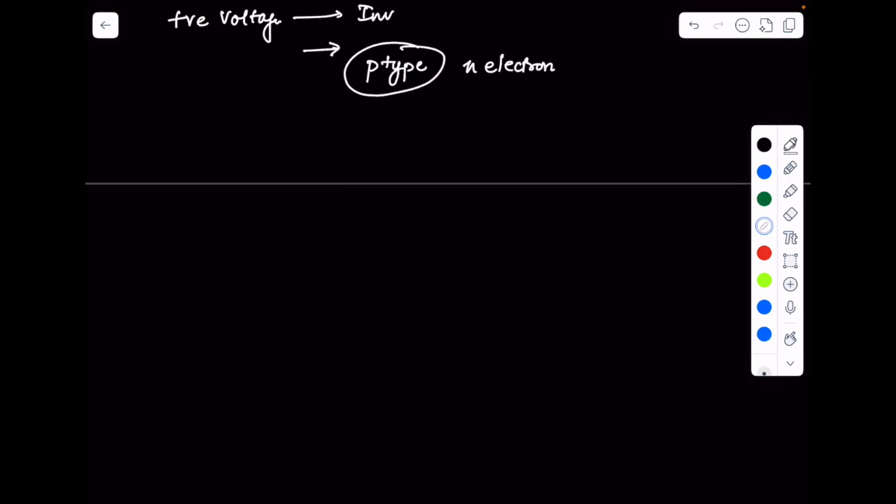So if you go back and look at the CV, you see that the C accumulation is 100 picofarads, right? And so therefore we have that A times epsilon ox by Tox, where epsilon ox by Tox is the capacitance per unit area. A times that is the net capacitance of the structure, 100 picofarads. And so I need to find the area.